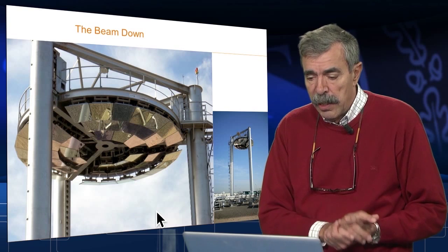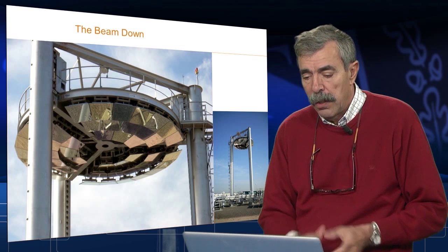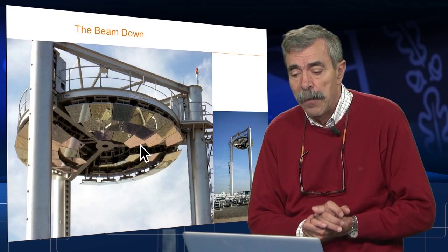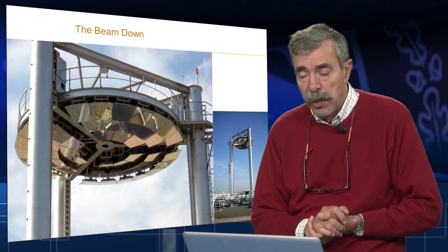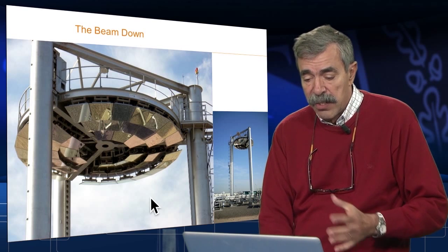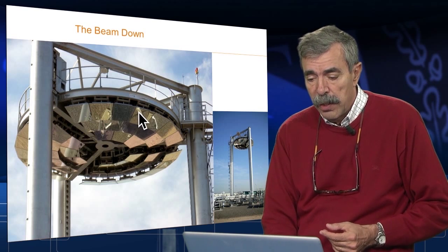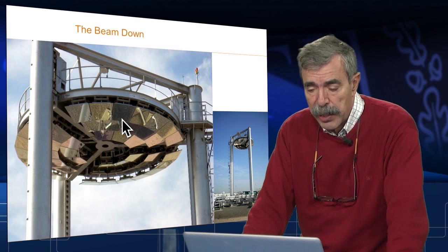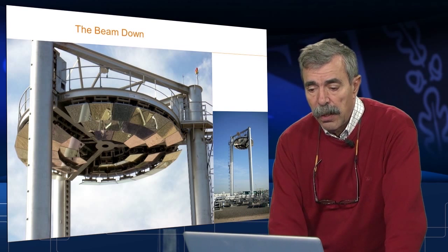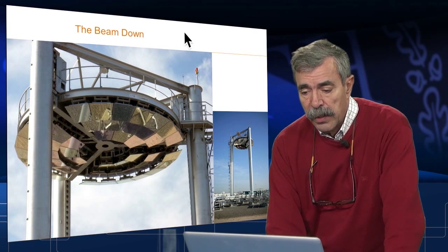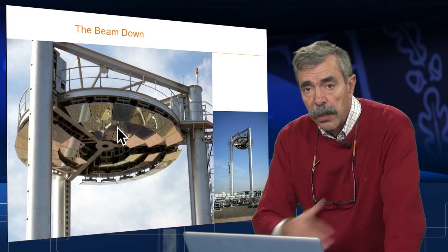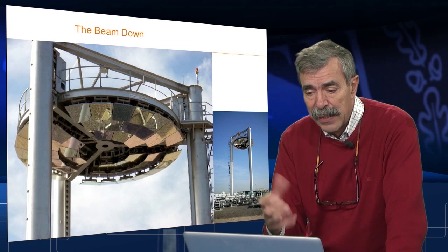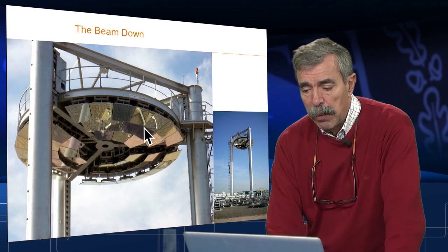And just to mention, in a small plant like Gema Solar, in the tower, we are receiving like 140 megawatts of thermal energy. So imagine that in a similar plant having this configuration, if those mirrors have just a 5% reflectivity factor, you need to be evacuating something like 7 megawatts of heat. So that obviously is a big problem.